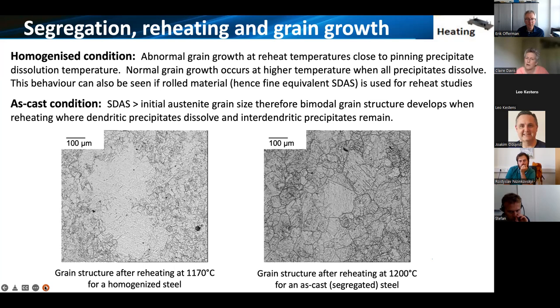And when we carried out reheating trials there, we actually found we could make the material show abnormal grain growth, because now when the grains started to grow, they had enough driving force, because it behaved almost as a homogeneous material, because the length scales between any of the segregated regions were very much finer.